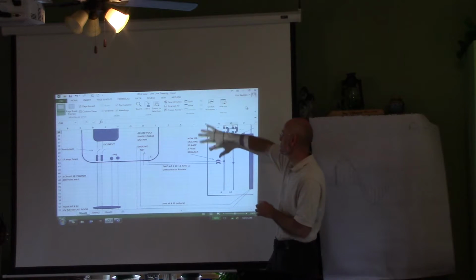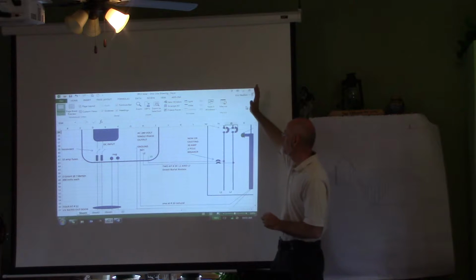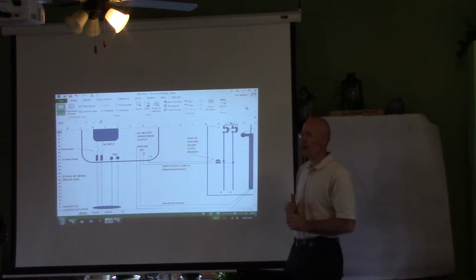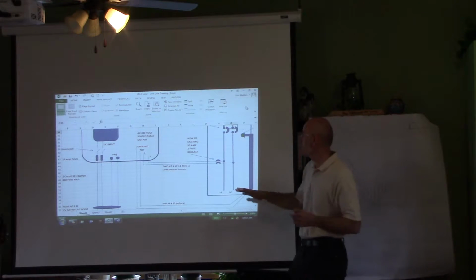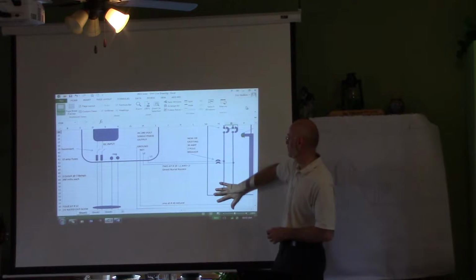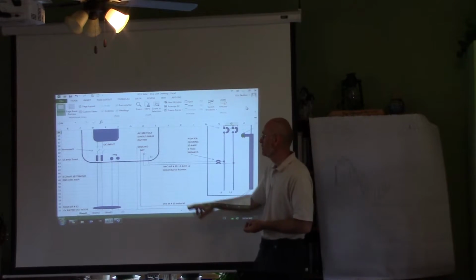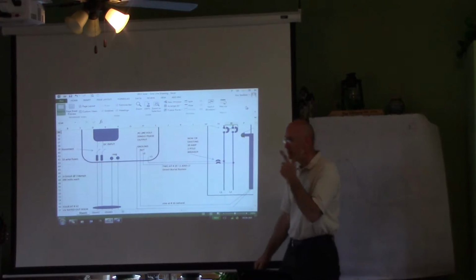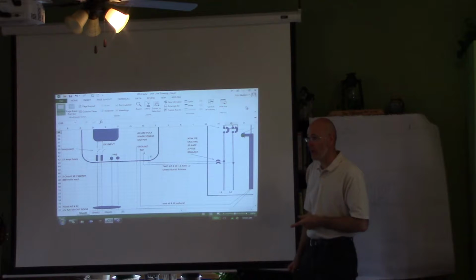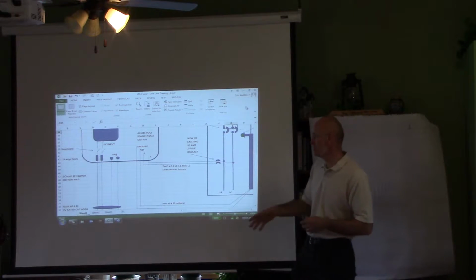So the inverter is going to stay off as long as the utility is knocked out. Okay, so the guys come out, they fix the pole, they turn the power back on, boom, start the timer. Power's back onto the house, this is off, power's coming from the utility like every normal house, count down to 5 minutes. When 5 minutes gets here, the inverter goes, yep, timer's over, do I have power? Yep, I've got power.